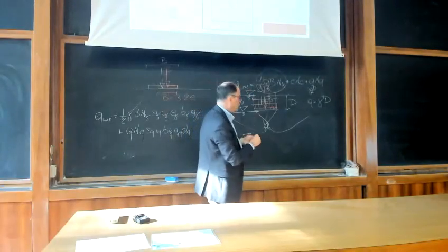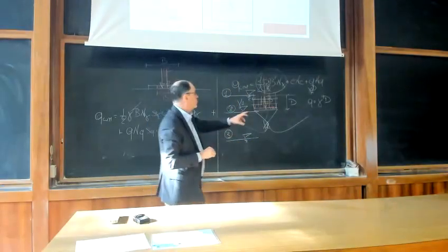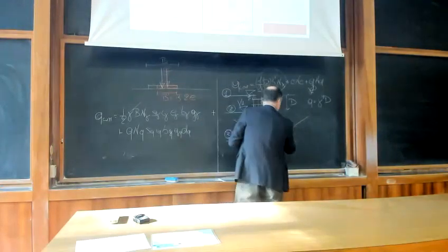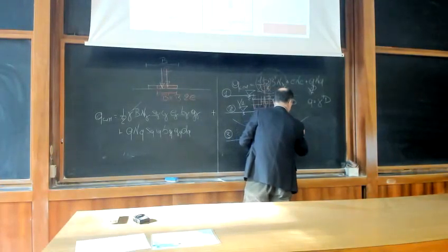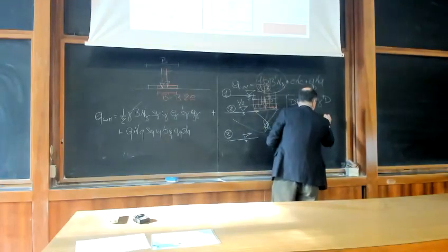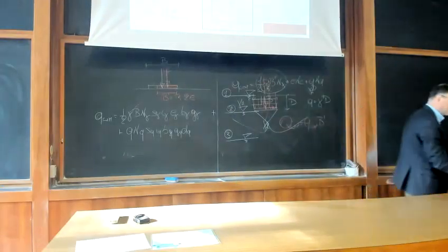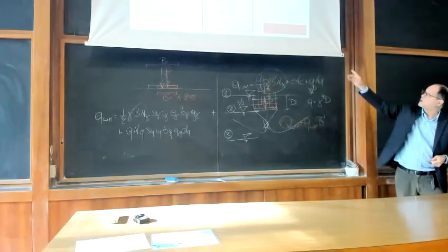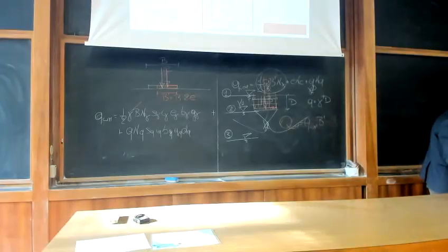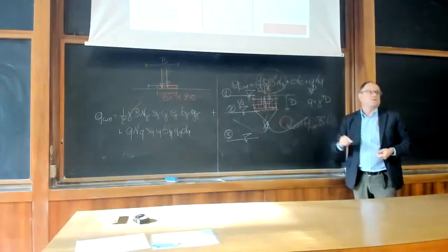But in this expression you have to consider B dash, which of course will influence the limit pressure and will also influence the total limit load, because then your Q limit is multiplied by B dash, and if you have an eccentricity also in the other direction, because as you see from this picture, if you have a rectangular footing with a double eccentricity on both sides, also L will be reduced in the same way in its direction.